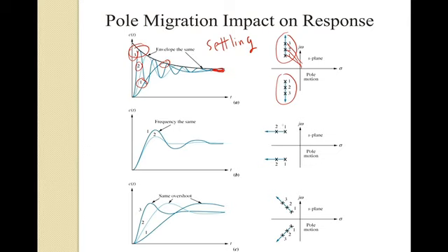Now we see these two cases for the peak time, along these horizontal trajectories here. Notice if I have a pole at location 1, I get maybe more overshoot. Why? Because my angle theta here is bigger than it is for theta 2.